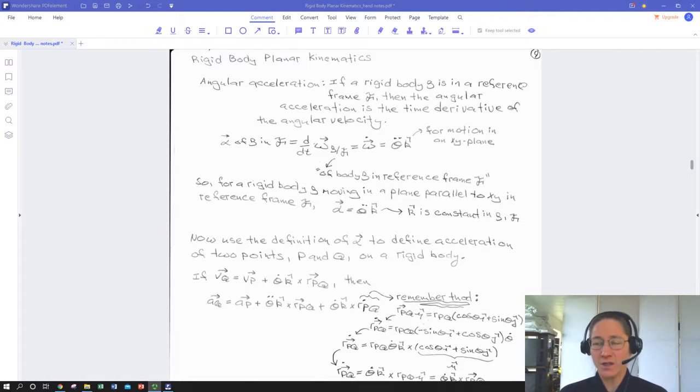So we're already starting to look a little bit at the idea of relative reference frames, because when we look at a rigid body's motion and we start to look at the 2 points that define that motion, connect them to make a line, and then look at how that line rotates, it's got to rotate versus something. It's rotating versus an external reference frame.